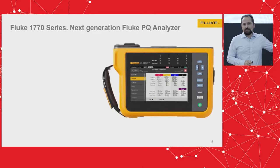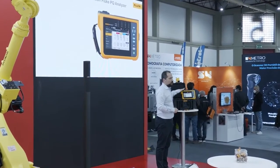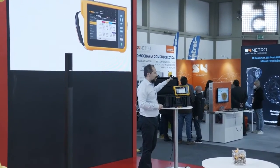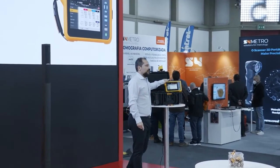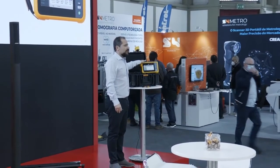Just a few words about our latest release, which is the 1770 series that you can see here, which is the most powerful power quality analyzers we have so far, capable of analyzing harmonics up to 30 kilohertz, sampling signals up to 20 mega samples per second. That's for transients, where we have really fast signal changes. It has plenty of communication interfaces, Wi-Fi, Bluetooth, GPS for transient synchronization, Ethernet, and so on and so forth.